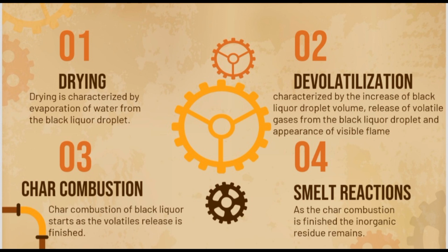The fourth is smelt reaction. As the char combustion is finished, the inorganic residue remains. The black liquor droplet has first melted and transformed to a liquid droplet. If oxygen contacts smelt, the sulfide in smelt is reoxidized to sodium sulfate, Na2SO4. In a recovery boiler, it is important to have a non-reacting material on top of the smelt to avoid smelt oxidation. Thank you. I return it to the moderator.